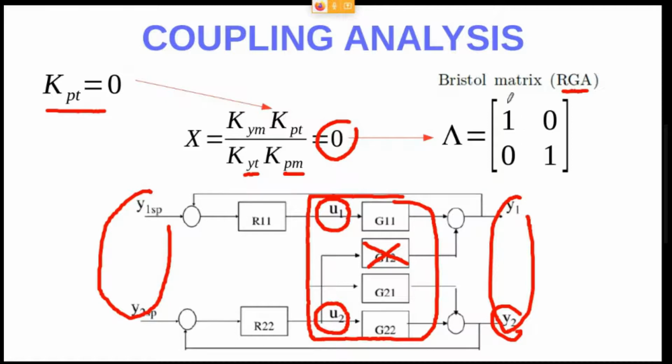So that's why this tells us that the proper association between variables will be: the main rotor will be used to affect the pitch angle, while the tail rotor will be used in order to affect the yaw angle, because we have no choice, because the tail rotor only affects this yaw angle, right?